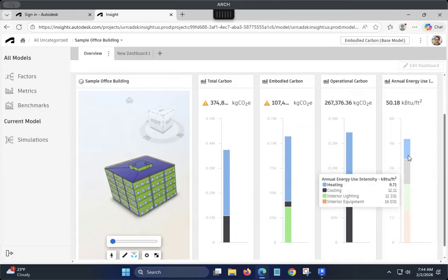You can see the decimal points throw me off a little bit. You can see it's actually a fairly even distribution of heating, cooling, interior lighting, and equipment taking up the most of the four. But in short, I could scrutinize it from here. I could say, I'm looking at this. We're talking about Boston. It can get pretty cold. Maybe I'm a little suspicious of the heating. This is where maybe the smell test comes into play. I need to look at my inputs, look at my system types, look at the different parameters I indicated, and just make sure from a quality control, quality assurance standpoint that everything is in there properly.